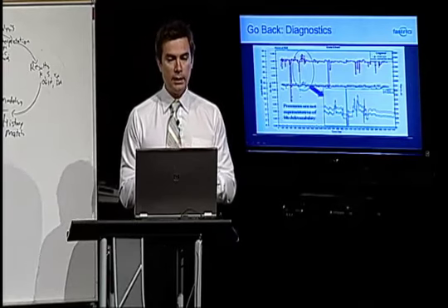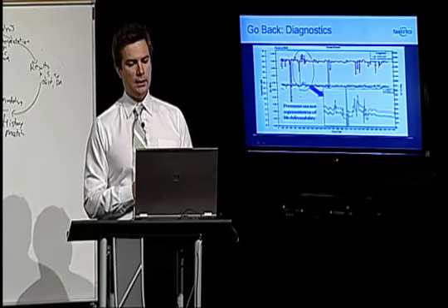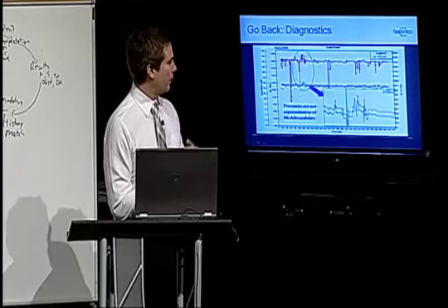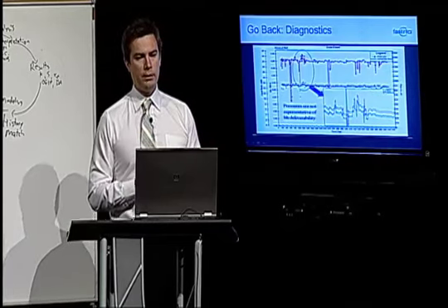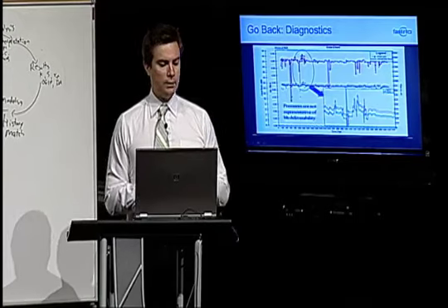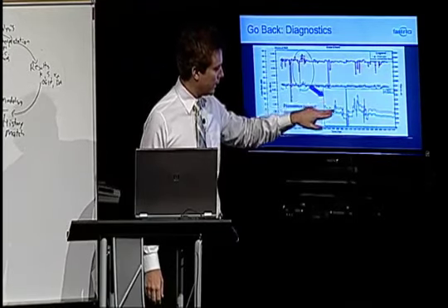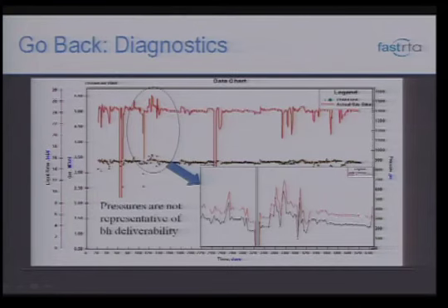But in many cases, especially in SCADA systems and electronically measured systems, we're going to get the rate and the pressure at roughly the same time. So if we get a production rate and a pressure, the diagnostic that we should always do is look at them and see how they're changing with respect to each other. And there's actually three ways that this can occur.